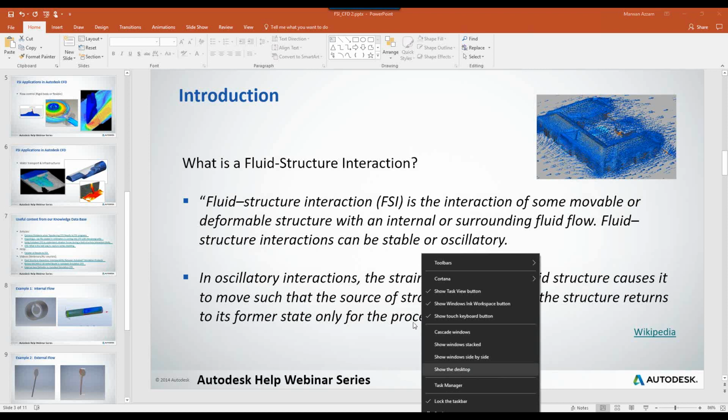All right. Thank you, Emil, first of all, for the introduction and the useful information. One thing I wanted to add to what Emil said is that running a model just inside of CFD inherently has fluid-to-structure interaction, because the fluid is bound by a structure, but that structure is considered to be rigid. We can calculate, let's say in a motion analysis or in a free surface or in any kind of analysis, if you don't have any boundary condition, that's considered to be a wall.